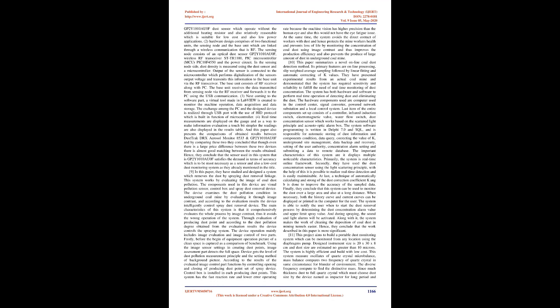Sensor selection, i.e., they have chosen the GP2Y1010-0F dust sensor, which operates without an additional heating resistor and is also relatively reasonable, which is suitable for low-cost and low-power applications. 2. Hardware design comprises 2 functional units, the sensing node and the base unit, which are linked through wireless communication, that is RF.